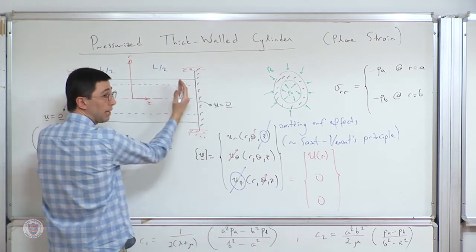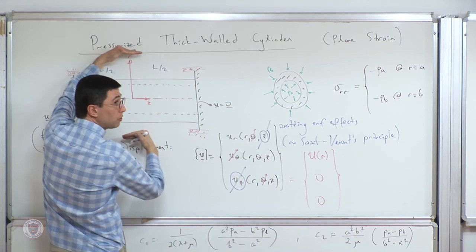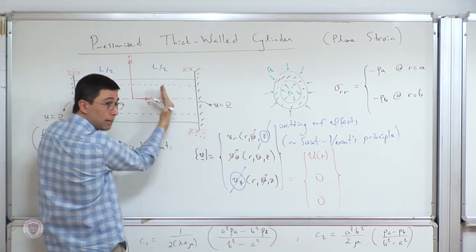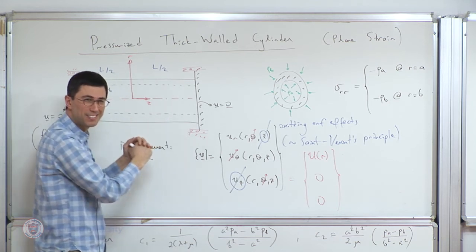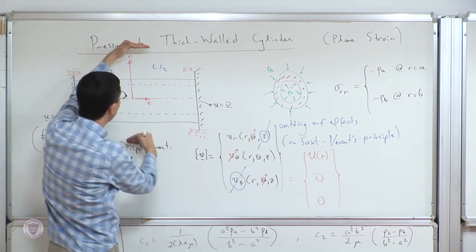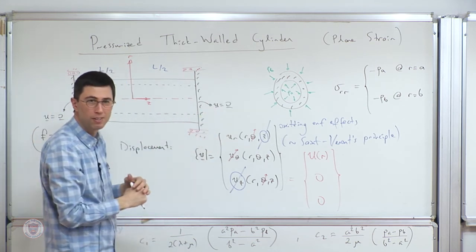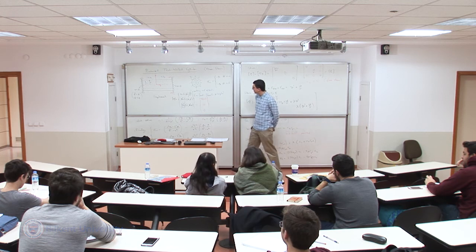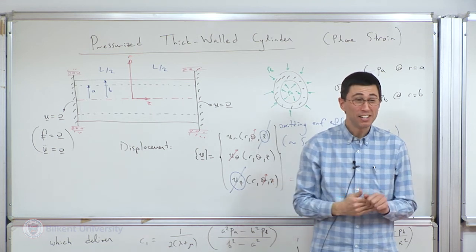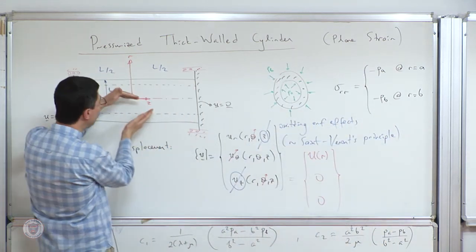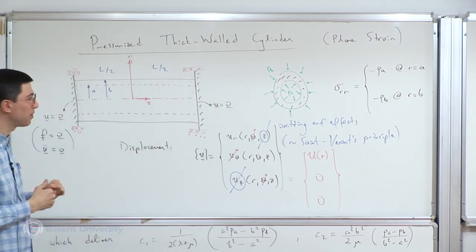But in this case, it can contract. So what happens is there is the pressure, it expands in the radial direction, and it tries to contract. Why is it trying to contract? As it tries to expand in the radial direction, could it be possible that it tries to get longer? Is it possible? I pull on a rod. Does it get thinner or thicker? Exactly, it depends. So can it get longer when I apply the pressure? Yes, it might, depending eventually on whatever the Poisson ratio is.